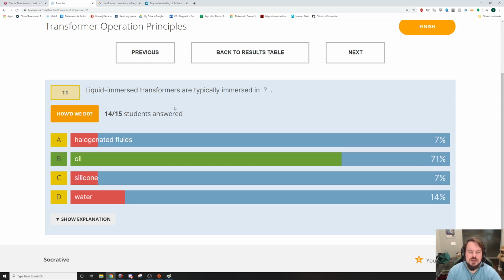If you know about heat rising, that's the same in liquids. So warm air rises, warm liquid rises. As the transformer heats up the oil will rise to the top and cool itself off, and it will actually circulate itself. You don't need an actual pump or anything to circulate the oil.